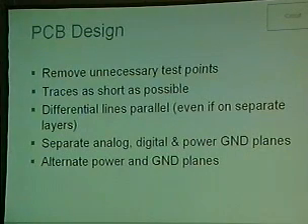Keeping the ground plane separate also helps with noise issues, and if you alternate the power and ground planes as you go through your layers, it helps add a little level of tamper detection if an attacker was trying to drill through your board to access some of the lines in the multi layers. They might drill through power and ground and possibly short those together.